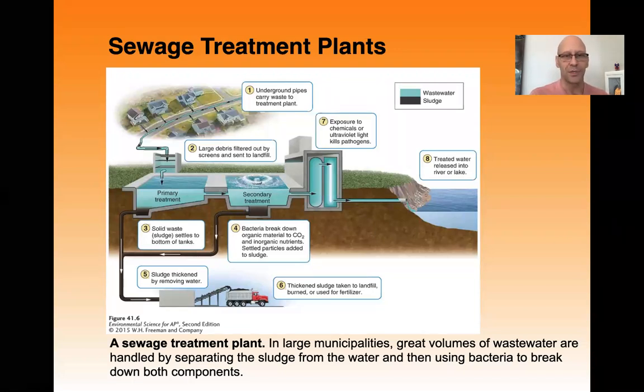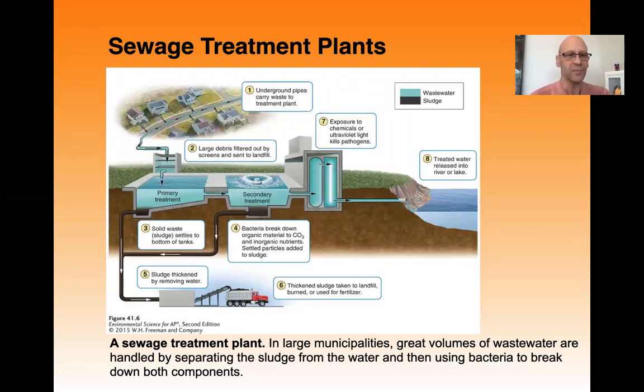So if we go back up to what's left after that initial primary settling, we have the secondary treatment, and they do the exact same thing. So whatever's left in the water is fed to bacteria. That bacteria consume anything that's left. There's an additive placed in the water, which essentially causes all of those bacteria to clump together until they're heavy enough to sink to the bottom. They then turn into the sludge, which is added to the fertilizer. Anything that's left is essentially clean water.